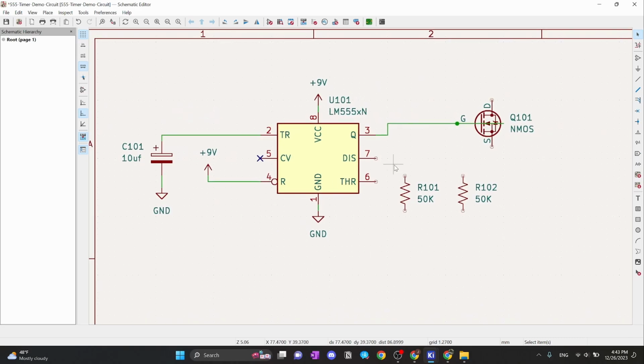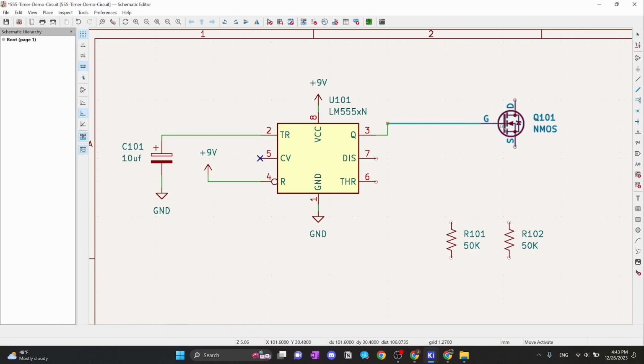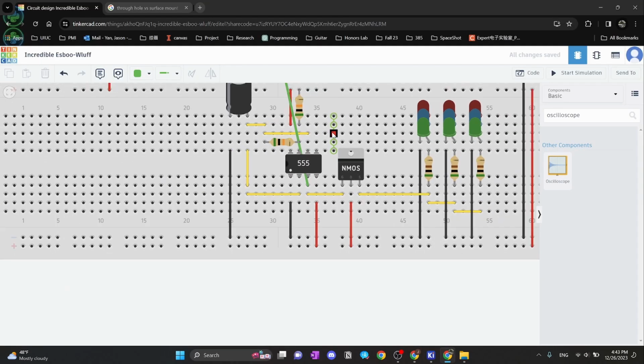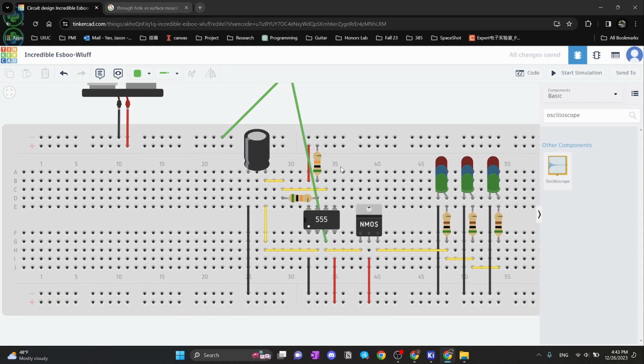Alright, pin 6 and 7 is actually a little bit complicated over here. Oops, that's bad. Sorry about that. Moving those lines may have weird implications behind them. Alright, so we can look at pin 6 first. It has a pretty simple connection. It just goes to the positive end of the capacitor, where pin 7 has a pull-up resistor, a resistor that's connected to power, and another resistor that's connected to basically pin 6.